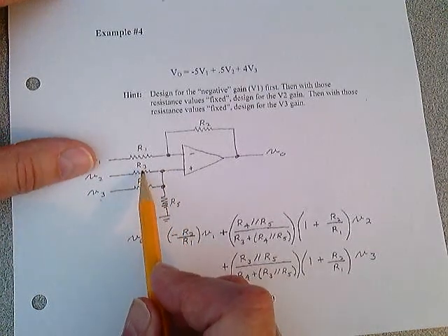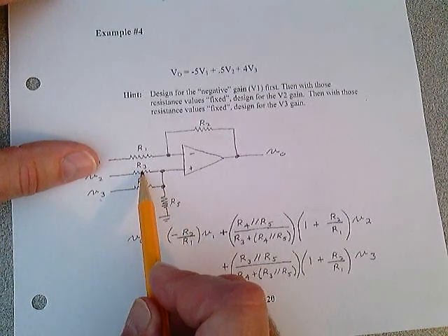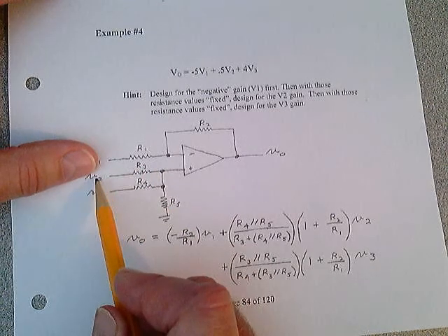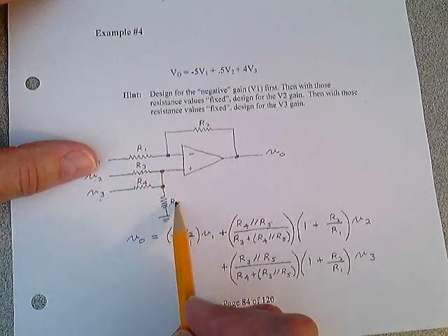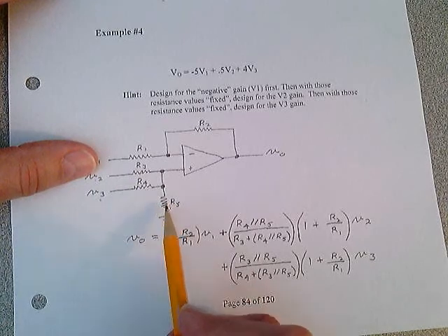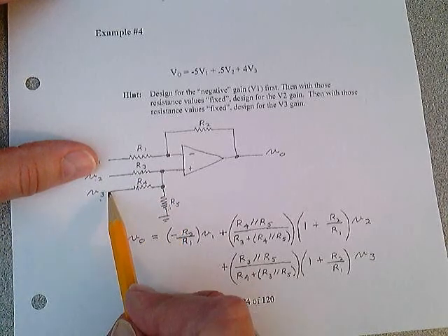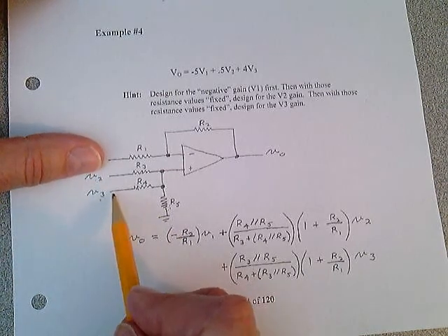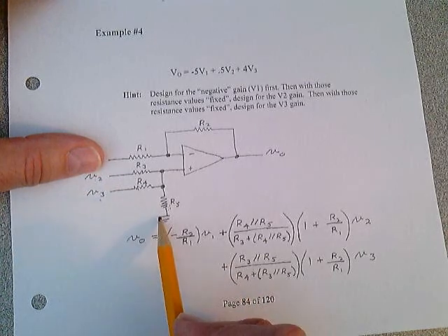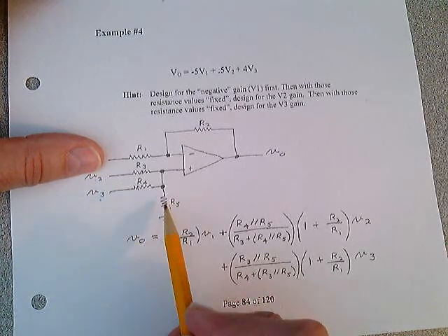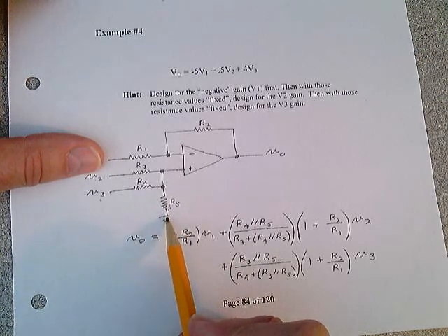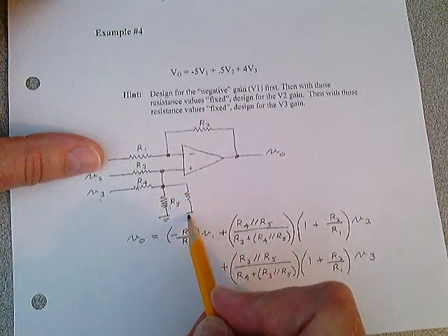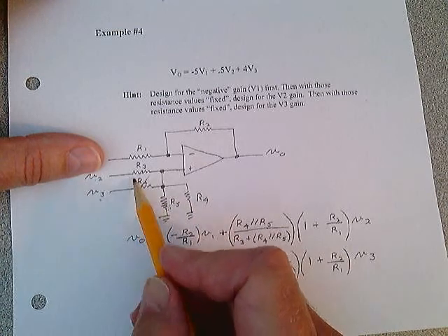But when you're taking into account R3, you have to be careful. It's not simply going to be the voltage proportion of V2 that makes it over here is not R5 over R3 plus R5. These are in parallel with one another. Remember the superposition rule where we can basically take this to ground. So if you're looking just at V2 here, think about this. Treat this side of the resistor going to ground like R5 is going to ground. If you see it a little better, maybe you just draw the R4 over here like this. Maybe it's easier for you to see and get rid of it up here.